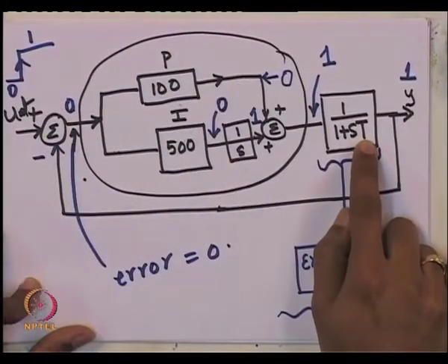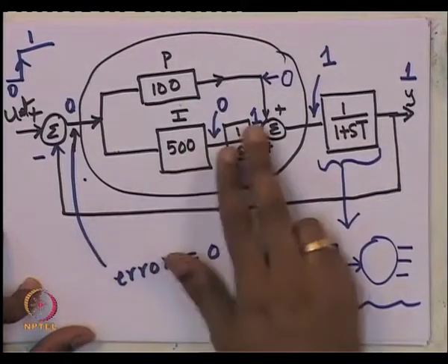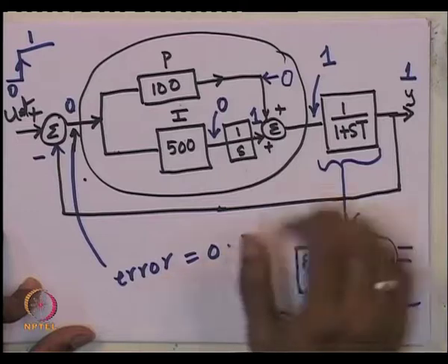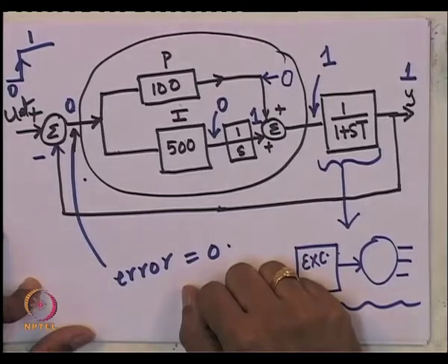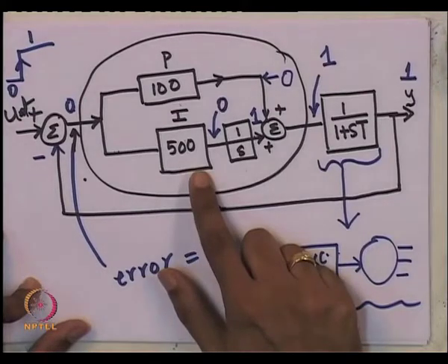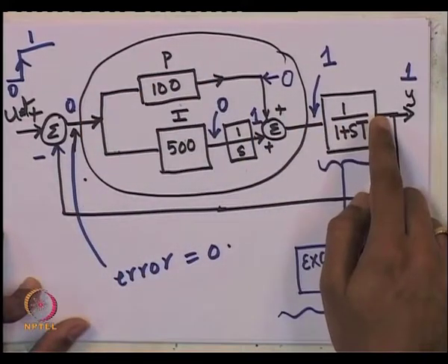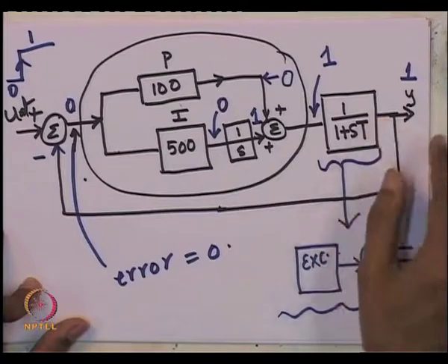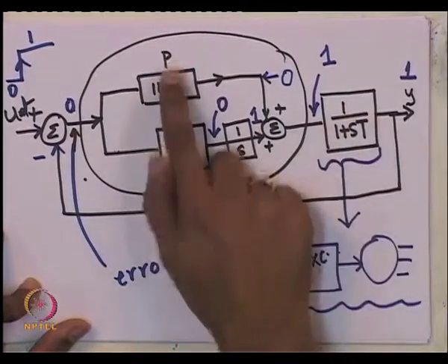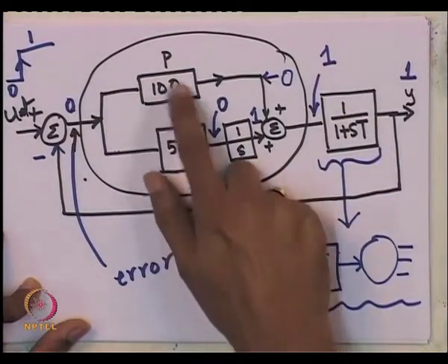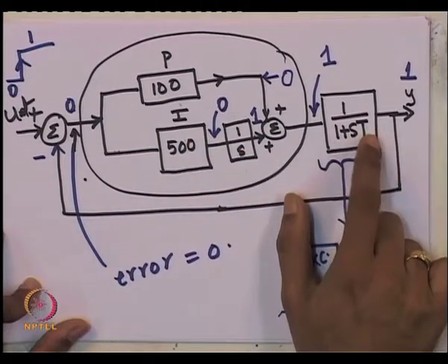Okay. If t is not greater than 0, then you can show that this particular unity feedback system is stable for any value of p and I. So, we can have a system of this kind which is stable. You can just verify this, that at least if I have just a proportional controller, it is easy to show that this system is always stable. So, this is something you can check out. Is it stable with just a proportional controller? Is it stable with a proportional integral controller, and what are the gains for which it is going to be stable in terms of this time constant t?